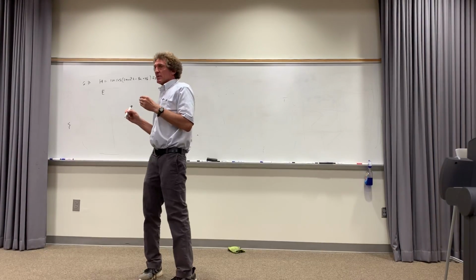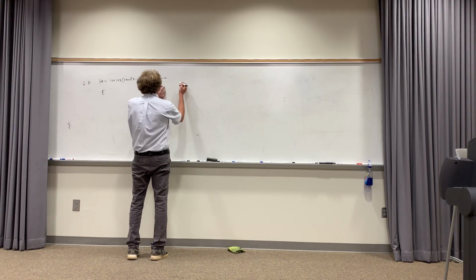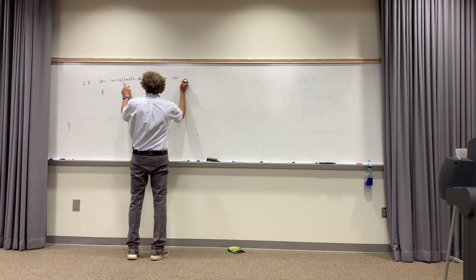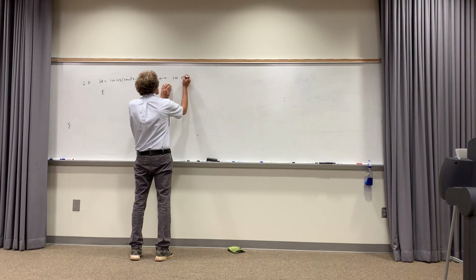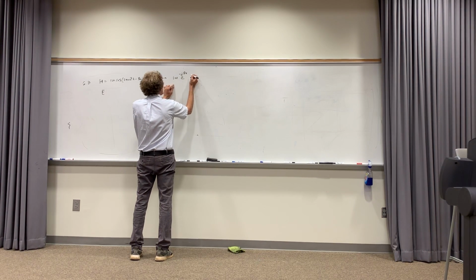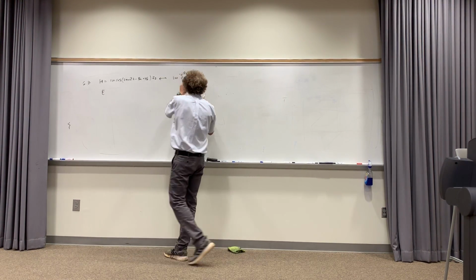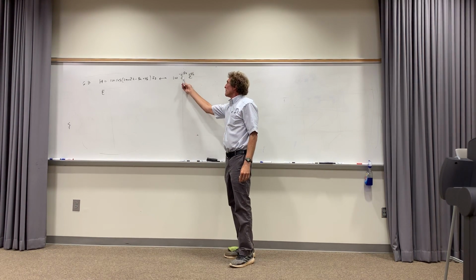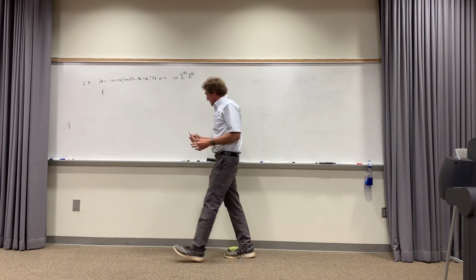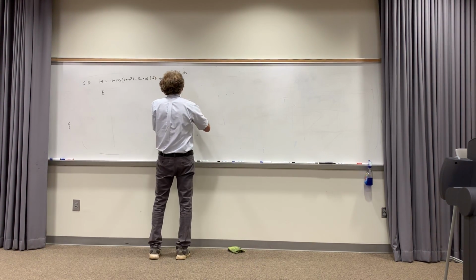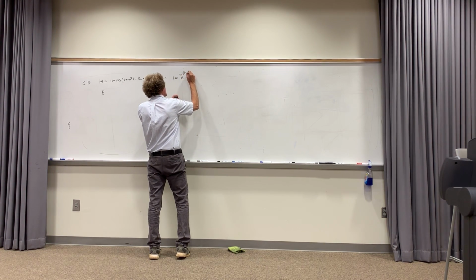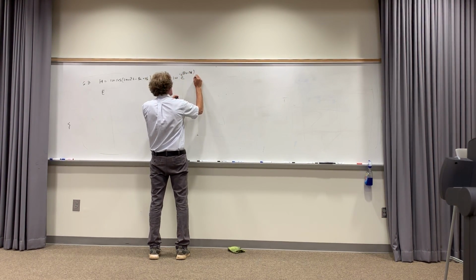To do it in a phasor, it's not going to be a function of time. It's simply going to be magnitude, 100. Then we suppress this term, it's going to be e to the minus j beta x, right? And it's going to be plus pi over 4. Since that's a phase angle, it's going to be e to the j pi over 4 here. Now I could lump that in there with the beta term as well. I could have minus j times parentheses beta x minus pi over 4. Matter of fact, I might as well do that. So it'd be beta x minus pi over 4. And it's in the az direction.